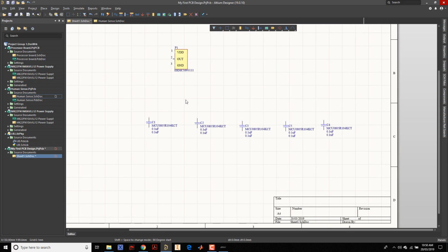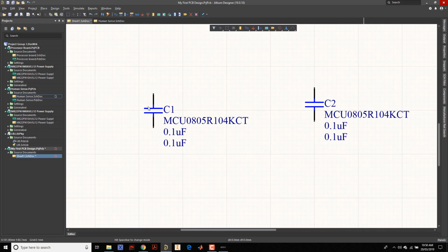So now to connect it, okay, these are the pins of the capacitor. To connect it, I can go here to this place wire. We are in the schematic, we are not routing, so I'll go to place wire, or I can use the same symbol around here, place wire. All right, I'll click on this, place that.